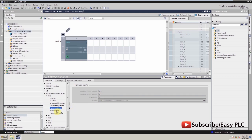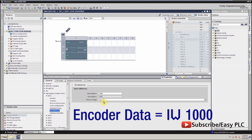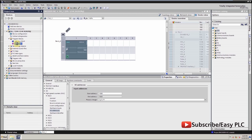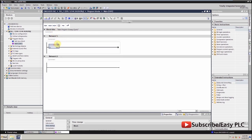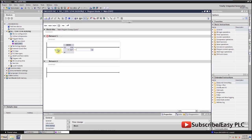Now if we go to the I/O addresses menu, there we can see the address from where we can get the encoder data. IW1000 is the address of the encoder. Now we will go to the programming block and do some programming. Drag and drop a move instruction on the ladder network. We will move encoder data from IW1000 to MD4 data register to make it available for making logic.